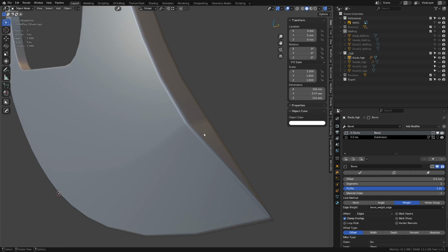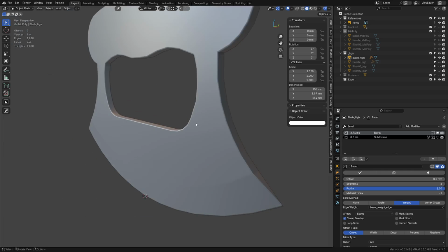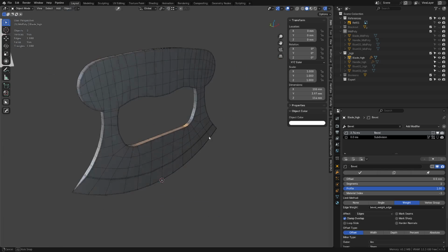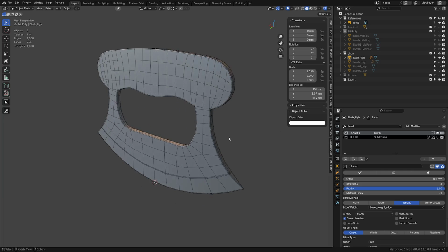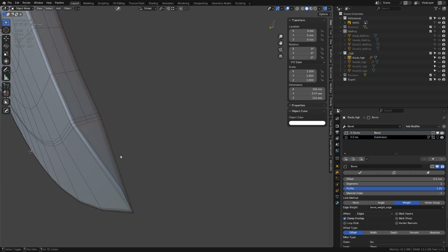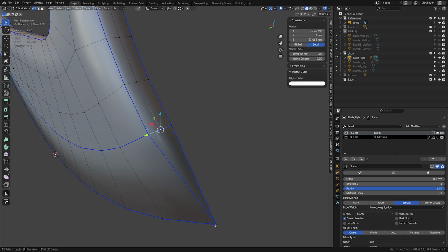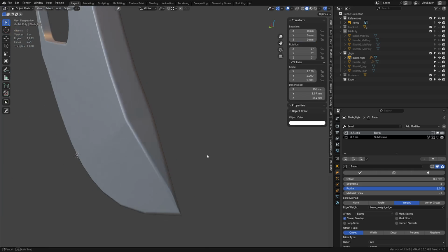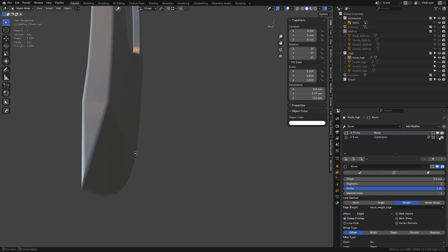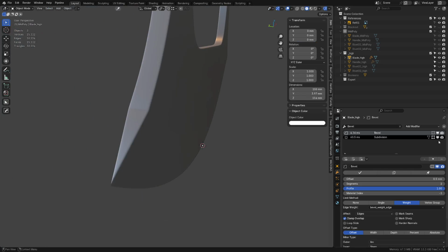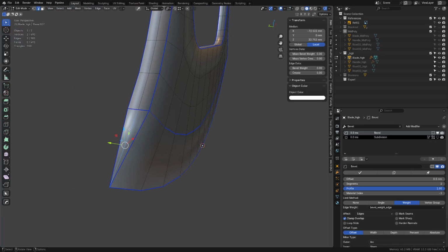But it kind of flattens out the curve here as well. We don't want that. So we're going to have to go destructive at some point with that bevel to fix things like that. And sometimes you might end up with a triangle or something. Like if this was connected, for example, through here, it won't do correct either, especially with the subdivision. It would start to look wrong. For whatever reason, it's not doing it, but whatever.